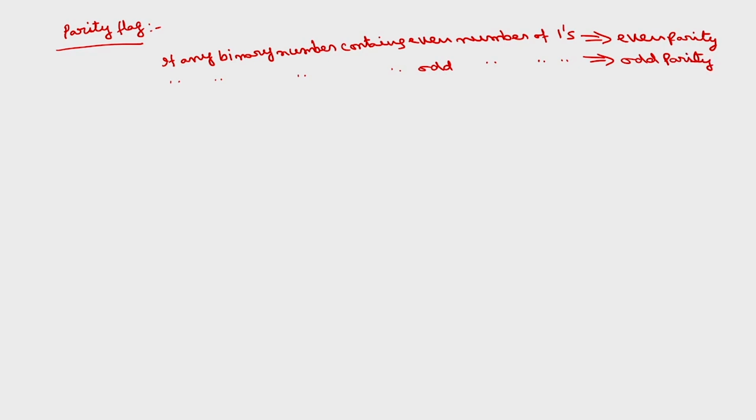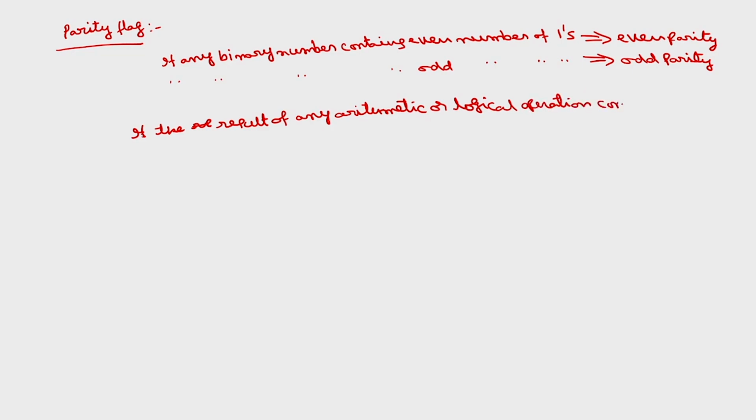Now, the condition for this parity flag to be set is: if the result of any arithmetic or logical operation contains an even number of ones, or even parity, then the parity flag will be set. Otherwise, the parity flag is reset.